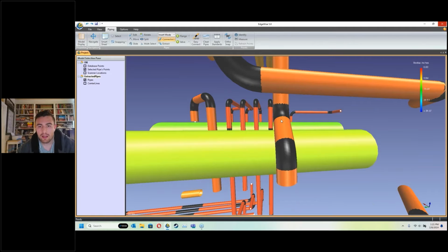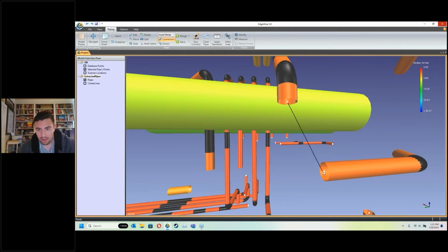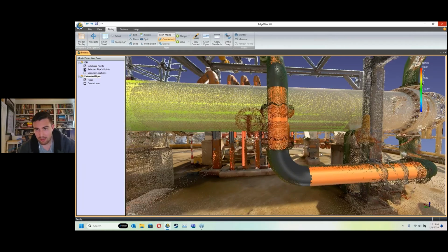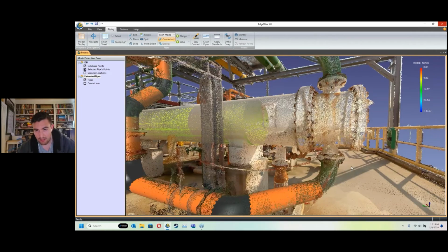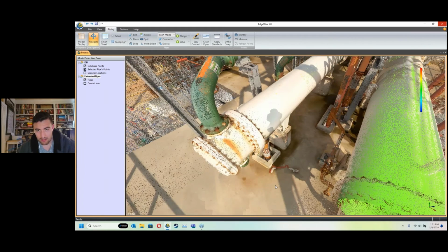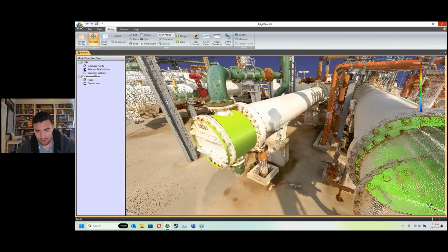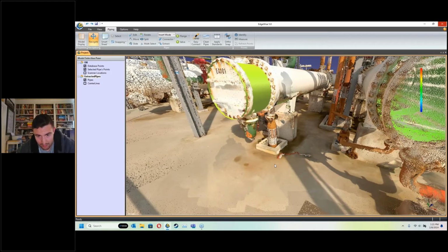You can capture about 600,000 points per second, and the range is 100 meters. These all come into play with how the SLAM algorithm operates and how you use unique geometry and vertical elements around you to keep the data tight and avoid drift errors or anything like that which can happen in SLAM.